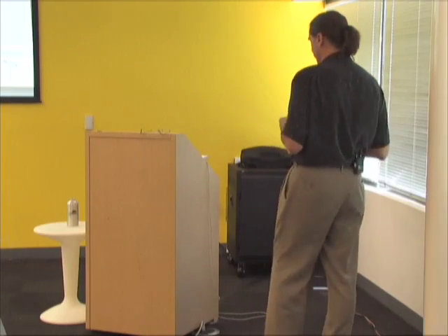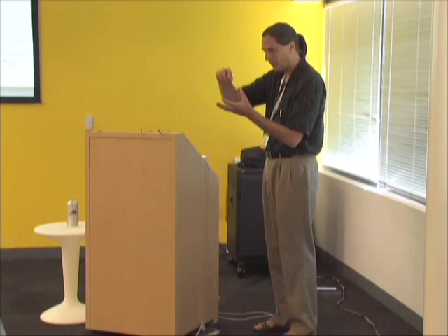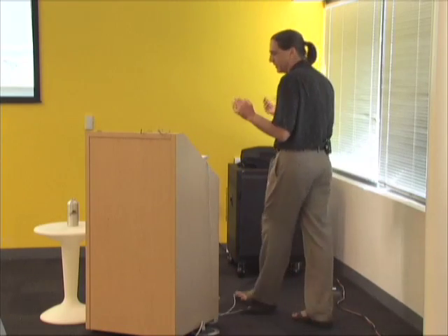And my last point on this is you really need to think about how much detail you need to show. In our work, we don't need to show every nut, bolt, and washer. That just adds so much complexity. These days, we're starting to get a lot of models back from vendors that are SolidWorks or Solid Edge models, and we always take them back, convert them into SketchUp models, and we can import them, but they're often 100 megs, 10 megs, and I'll find every bolt hole has every thread on it. Every nut has every thread, and you get rid of that, and we get a 100K file. It's much easier to work with.